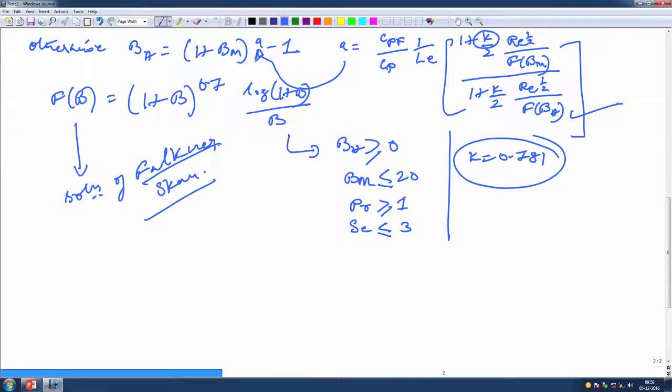So, this is a really ingenious way that Sirignano and Abramzon used to solve it. They took the droplet piecewise, locally behaving like a Faulkner-Skan type of solution. Locally they are like wedges, right. And then they used the similarity profile, the similarity solutions that we did in the last lecture, f''' + f f'' = 0. That similarity kind of solution, of course in Faulkner-Skan, is a little bit different. They use that to find expressions for Nusselt number, Sherwood number, mass flux, because that is what you need for this class of solutions.